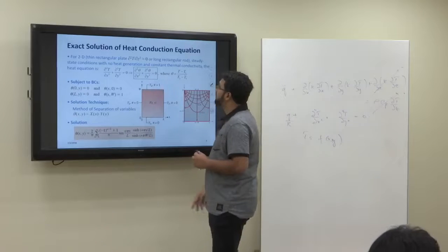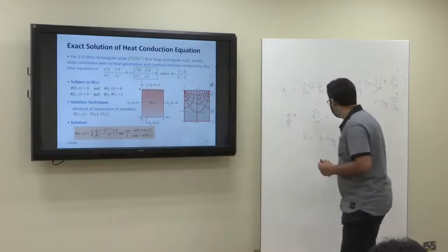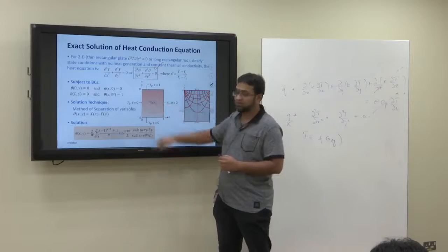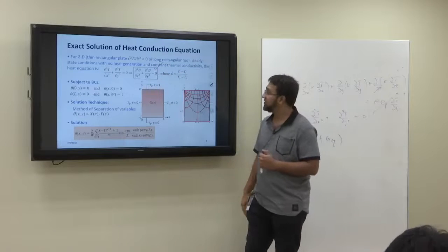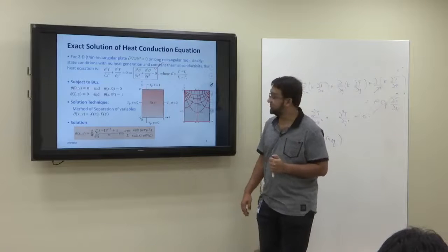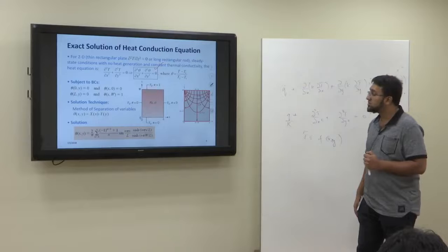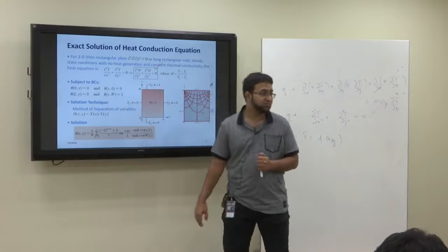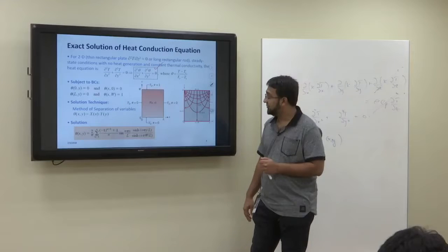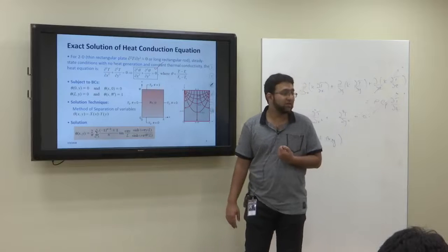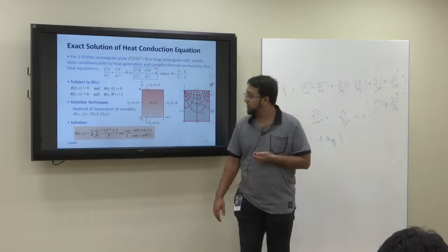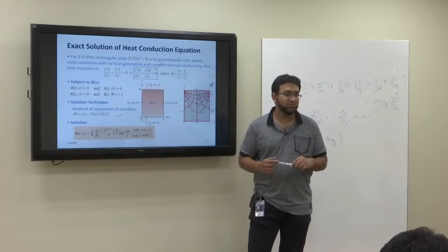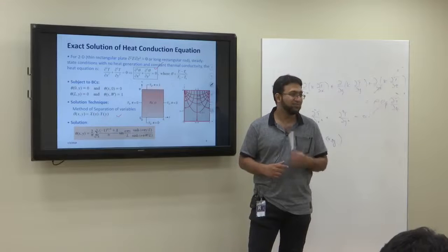So as we developed here, what we want is to solve this equation, if there is no internal heat generation: ∂²θ/∂x² plus ∂²θ/∂y² equals 0. And we need then 4 boundary conditions at least. And what is the methodology if we want to solve it analytically? Then by using the method of separation of variables you can solve. Do you remember the method of separation of variables? You might have gone through it. The x together and y together.